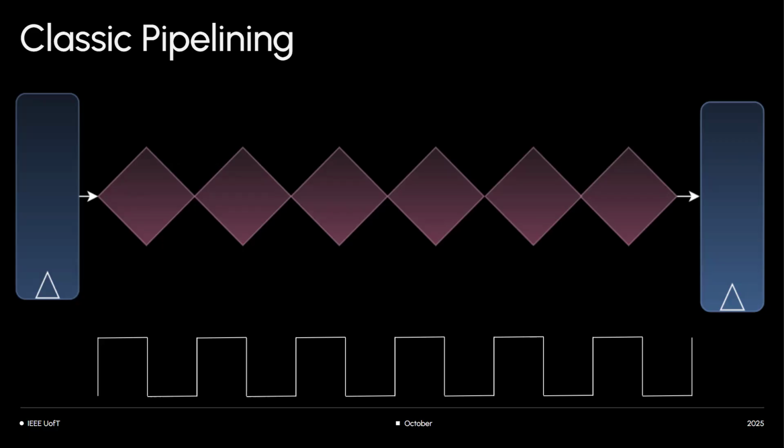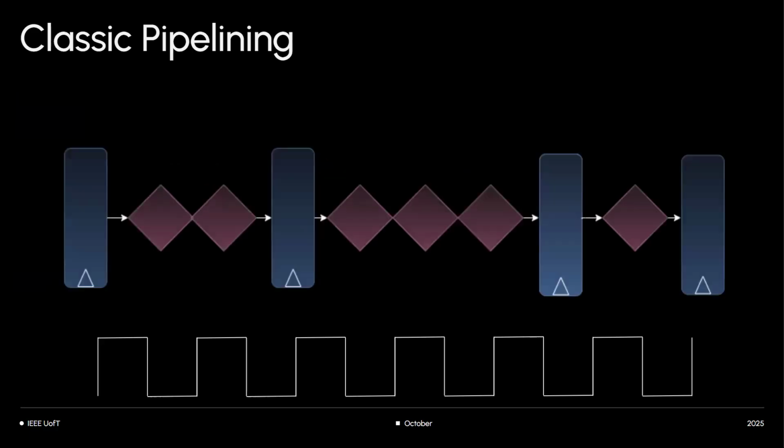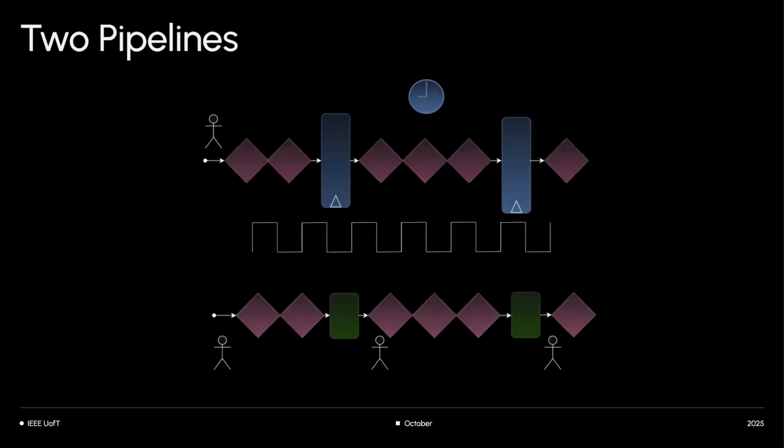So this whole idea of the clocked world is super restrictive. It's super simple at first. It looks like, oh, I just clock everything and let the EDA tools take care of it. But you see how much of a performance killer it is. In the second case, you saw how to make these local handshakes, this concurrency and nice collaboration, as opposed to something dictatorial, clock bang. That's the difference between a synchronous pipeline and an asynchronous pipeline, where people are actually being concurrent and not waiting for any clock tick.